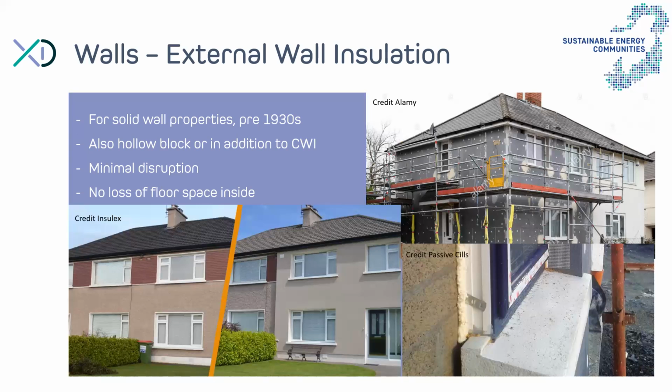There are a lot of advantages in external wall insulation. One, it's like a full wrap of the home. It deals very well with what we call thermal bridging, and I'll come back to you on that in a moment again. And you can add maybe 10 centimeters, 15 centimeters. In some cases, you can go as far as 20 centimeters, but 10 centimeters is already a fantastic achievement. And that doesn't take into the internal space, and there is minimal disruption, at least internally within the house. People don't have to move out when it's done.